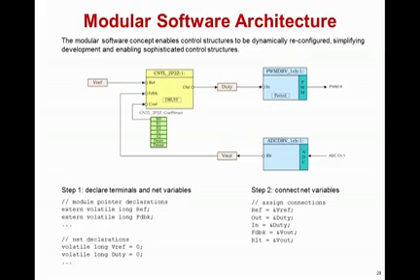Similarly, we can read in a value on ADC channel 1 and store that into a variable Vout. The way that we get these variables in and out of the various functions is with the use of pointers, which you can see on the right-hand side. The various pointers are set to values, vref, vout, and duty, and these are then assigned to the inputs and outputs of the various functions.